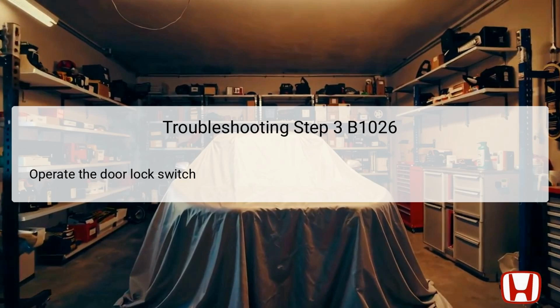This action tests the functionality of the switch and its ability to send the correct signals to the MICU. Observing the switch while operating it gives insight into whether it's mechanically sound or if it's stuck. A responsive switch suggests that the issue might lie elsewhere within the locking mechanism or wiring. Conversely, a lack of response could confirm that the switch is indeed faulty. This step also helps in assessing if the problem is intermittent or consistent, guiding the technician towards the next steps.